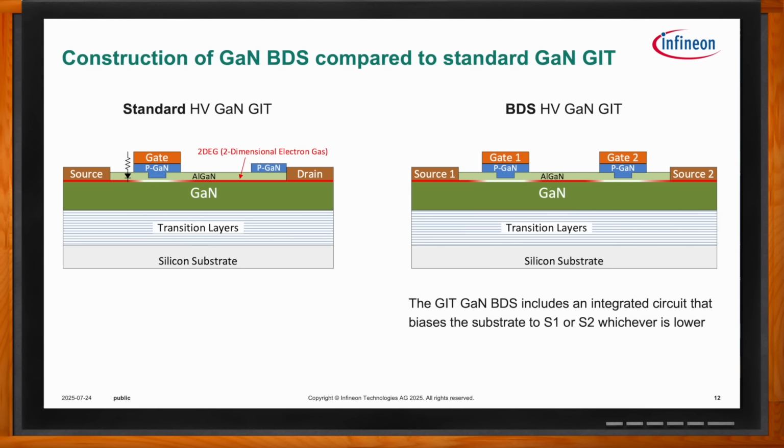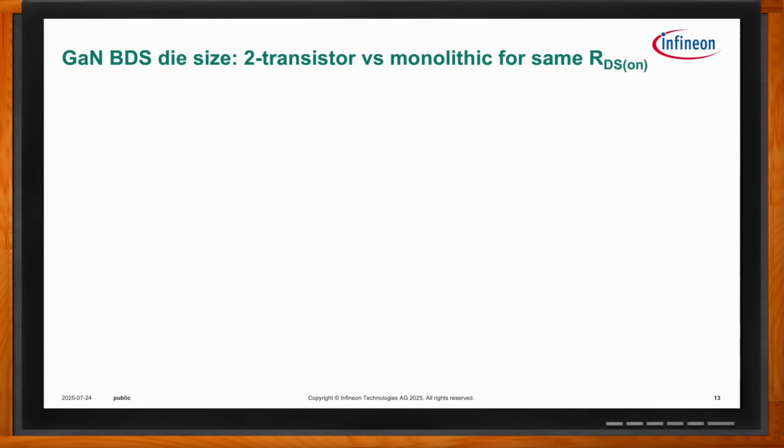So, Eric, the way it's drawn here, it looks like the BDS is actually a little bit bigger than the unidirectional switch. I thought you mentioned earlier that the BDS is smaller than unidirectional switches. Right. And this is the challenge to explain. So you're exactly right. This is, I said, 15% longer. So when we look at the cross section this way, you can see that the BDS has stretched a bit to accommodate that second gate. But let's now go to comparing the top view.